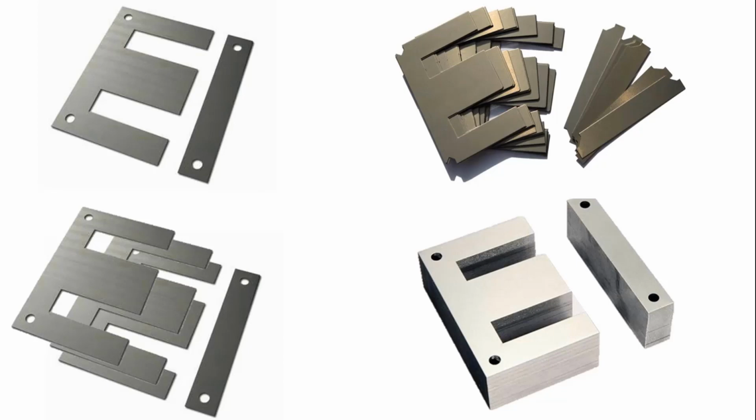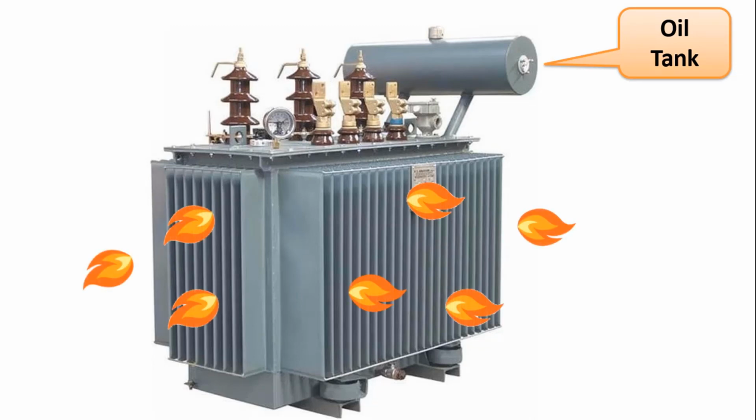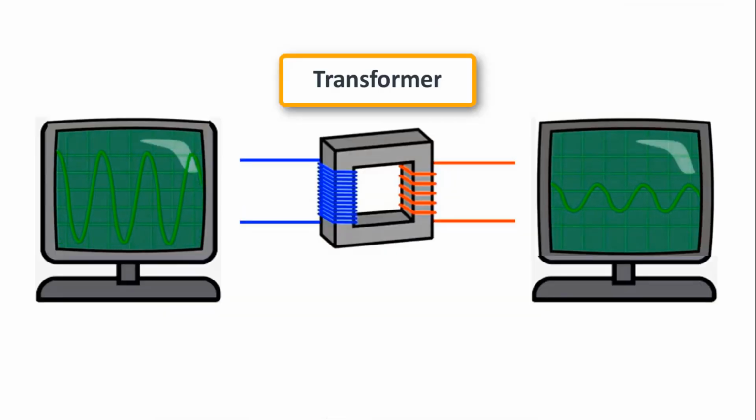In very large transformers used in power plants, overheating will occur, as lowering or boosting processes are carried out at high voltages. In order to dissipate this heat, oil is passed through it and cooling is provided. Therefore, such transformers have an oil tank. This tank is used to store the oil used for the cooling process. In addition, this oil also provides insulation inside the transformer. This is the basic structure and working logic of the transformer.